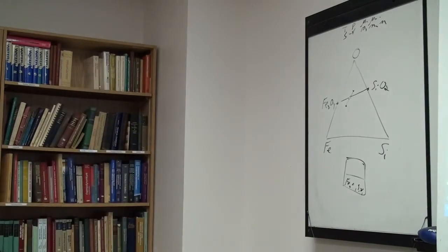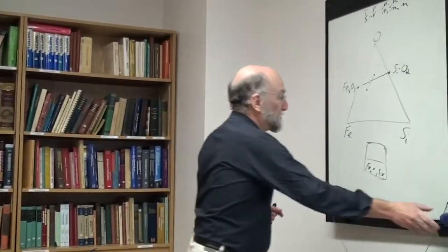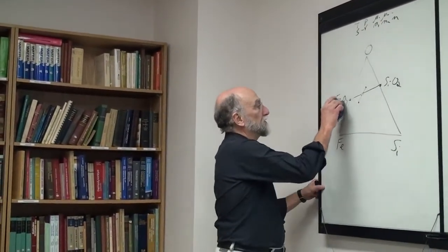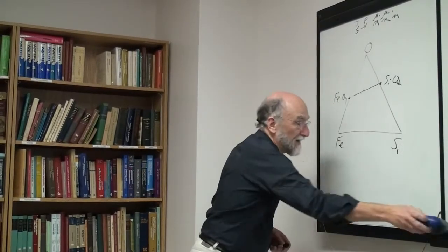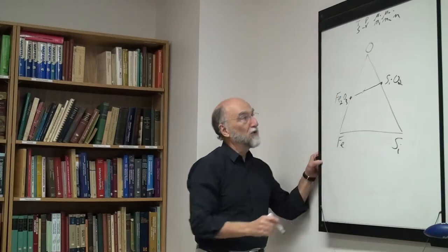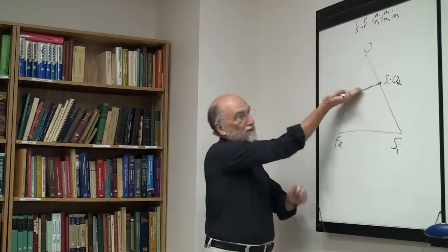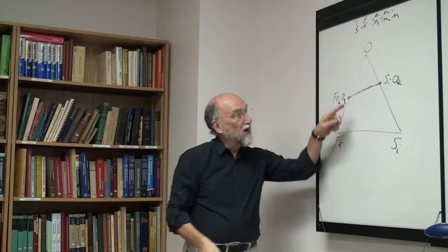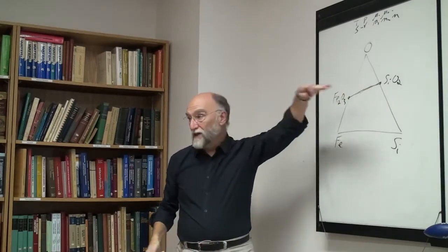Okay, in this diagram, this is called the Fe2O3 SiO2 at constant PO2. Okay, so PO2 is 0.21 bar, so this is the Fe2O3 SiO2 diagram in air. And this is very, very different from an isoplethal section. An isoplethal section, I could draw it, I haven't done it, but it would be simply the same thing. I start at Fe2O3 over here, and I draw a line. I start off with Fe2O3 in silica, and I heat the thing up.